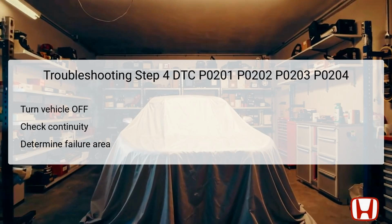Start by turning the vehicle to the off, lock mode for safety. Make sure the injector connector for the problematic cylinder is still disconnected. Now, check for continuity between connector test points 1 and 2. If continuity is present, it indicates that the wiring is intact and you can proceed to the next step.